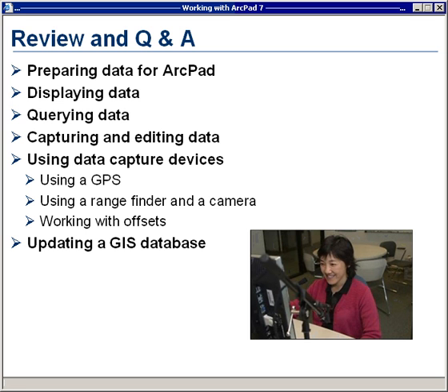Brent from Richmond Hill asks, is there a ratio between increasing the PDOP value and the resulting decrease in accuracy? In other words, if you increase the PDOP by 1, does the accuracy decrease by, say, 1 meter? In practical terms, there are many factors that impact the accuracy of your GPS position.